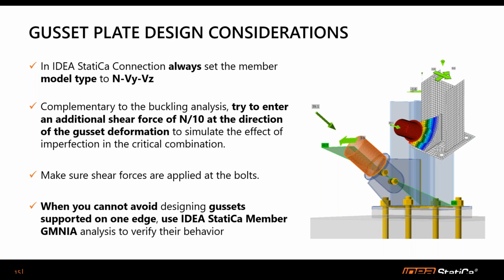The magnitude of this shear force is 1/10 of the axial force, and it should be applied in the direction of the gusset deformation, as I'm showing in this picture here. And of course, if you're going to use this approach, you should make sure that the shear force is applied at the center of the bolt.